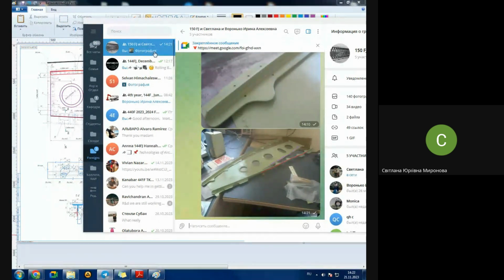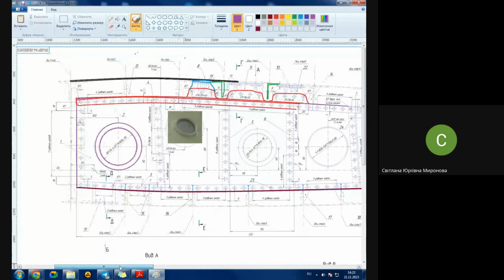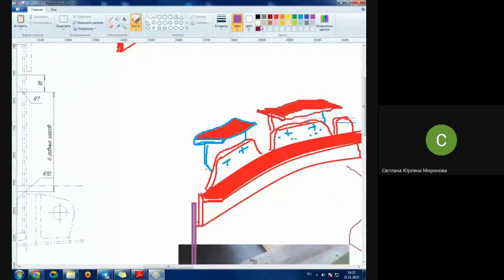In addition, I remind you that we have not only special jigs, but we have also so-called readjustable jigs, which might be used for a batch of ribs, for instance. Next, they are readjusted for a batch of other ribs, and so on. Let's continue. As I said, we are going to talk about jigs, but we're yet on the way to the idea of a jig at all. So we are going to place the web here somehow, preserving this little clearance